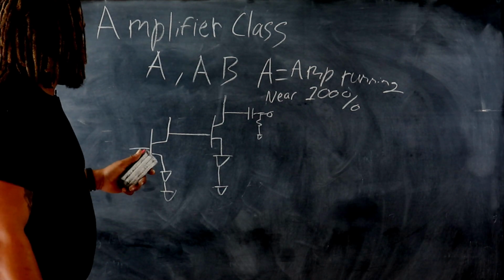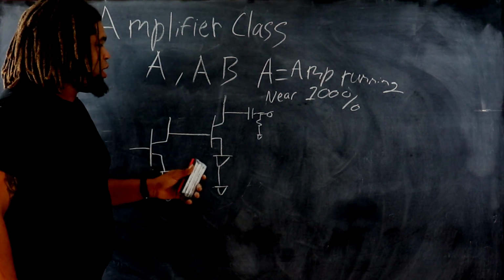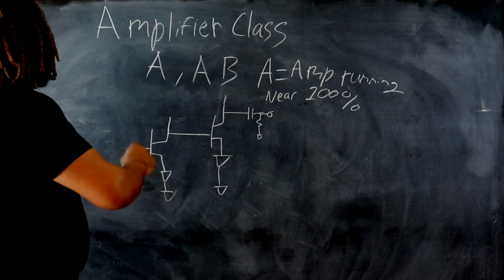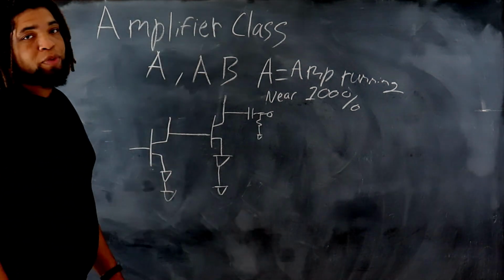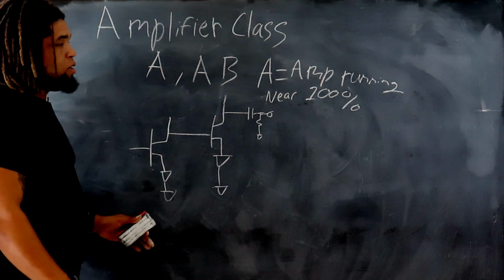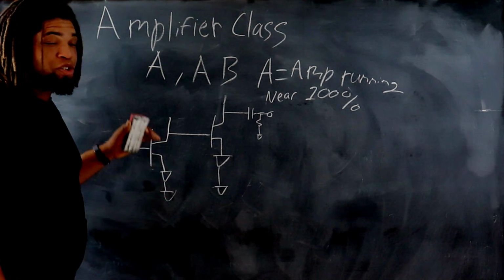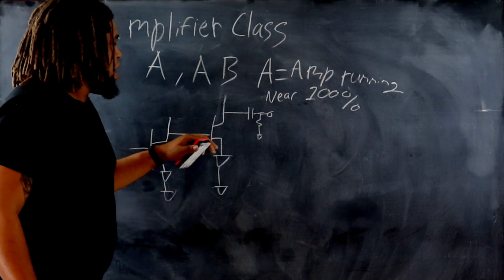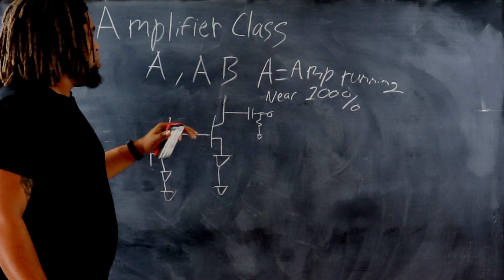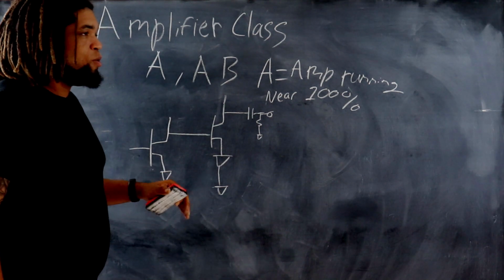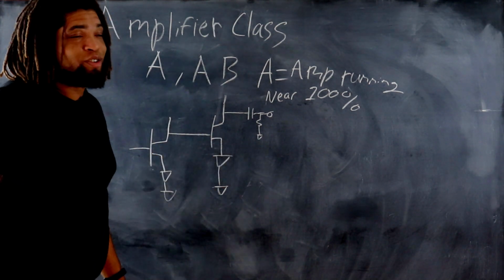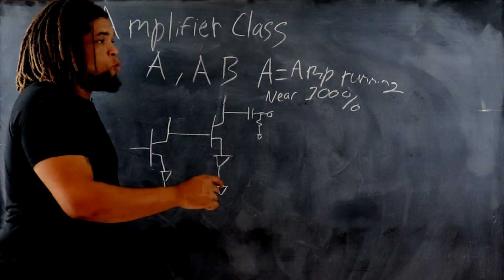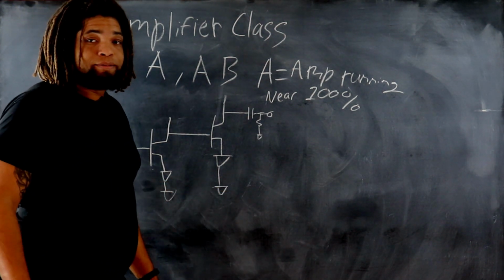So what happens here with the Class A amplifier in the transistor world is that it needs a lot of high current. So that means you have to have what? A big power transformer, right? So you have a big power transformer, which is also very heavy and expensive. Then you have all that energy going into a transistor or a couple parallel transistors that's now taking that energy and wasting it in the heat sinks.